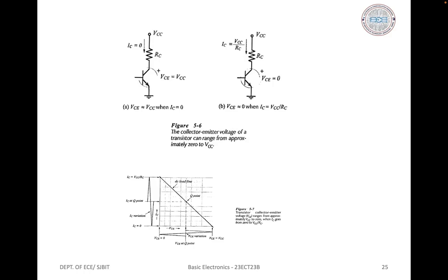So the DC bias point or Q point. The DC bias point, or quiescent point, also known as the DC operating point, identifies the transistor collector current and collector-emitter voltage when there is no input signal at the base terminal. Thus, it defines the DC conditions in the circuit. When a signal is applied to the transistor base, IB varies according to the instantaneous amplitude of the signal. This causes IC to vary and consequently produces a variation in VCE.